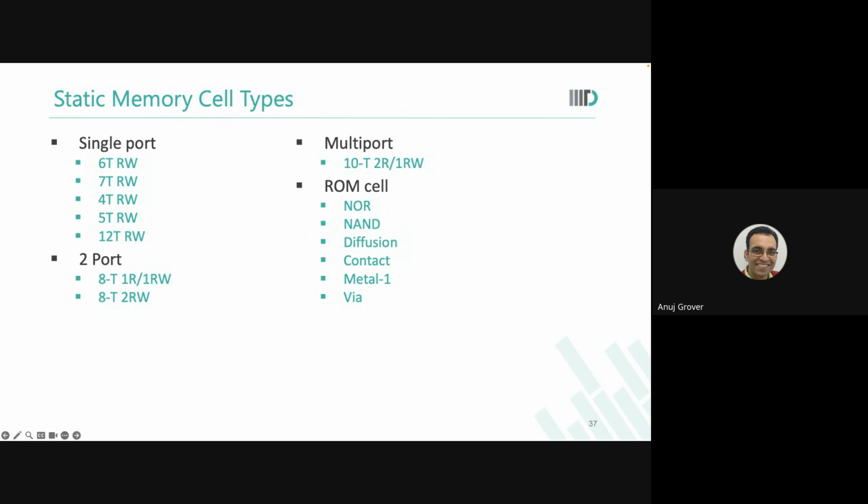But if it was a VIA1 ROM, then until Metal 1, everything is still fine. Only the wafers which have crossed VIA1 need to be wasted. So in those terms also, a higher level of programmation, even when you are running full steam, is helpful. Is this clear? Both aspects. In the first, you have more time to design, and the second is that if some mistake is found, fewer lots will get wasted.